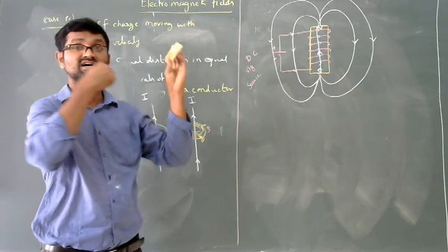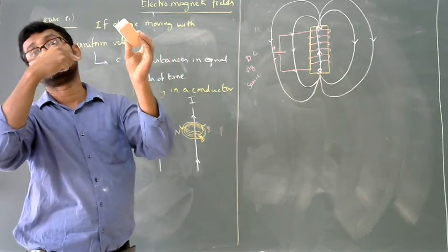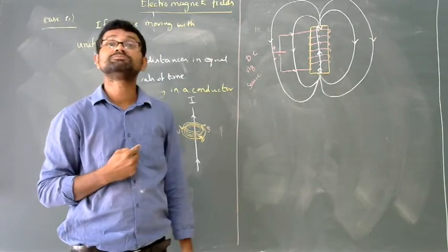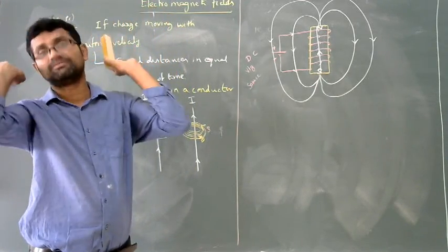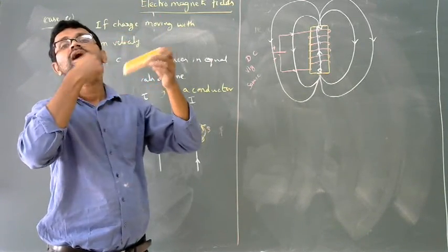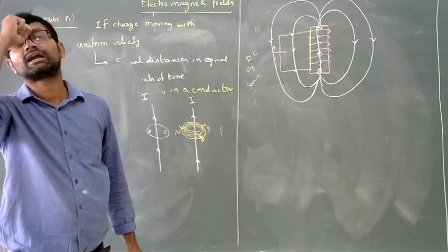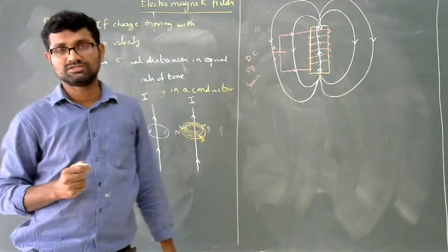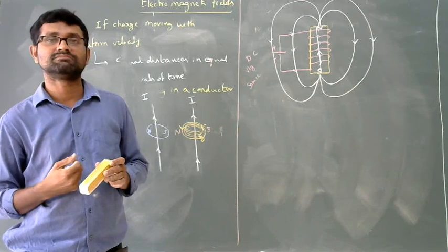If any two lines are there and both are carrying current in the same direction, then attraction forces are there. That's why in transmission lines, we do not let two lines carry current in the same direction at all times. A three-phase system is nothing but this: at one time, current flows from one phase to another phase, and after some degrees from that phase to another phase, like that current interchange happens between the three conductors. That's why we can avoid their attraction or repulsion forces. For some period there is attraction and for some period repulsion, and with that we can maintain the balanced system.